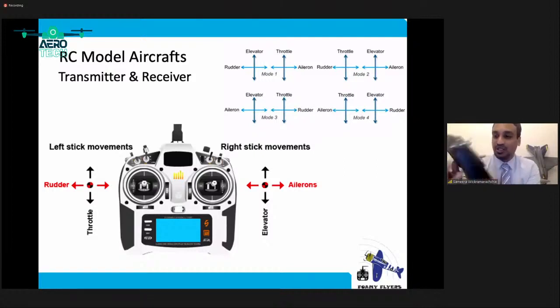That's how you normally know that the aircraft is totally balanced and has not got any issues. Normally there will be adverse effects like wind effects, ground effects, and things like that. But apart from that, when you're used to flying an aircraft, you know this one is going slightly towards left or slightly towards right. So you just do a trim correction and get it corrected.